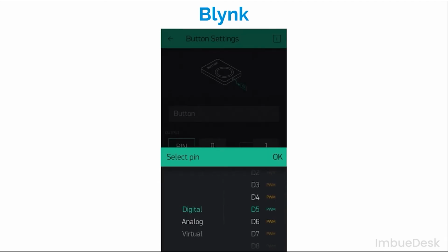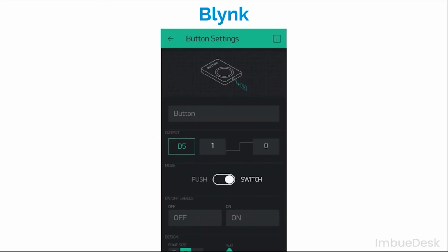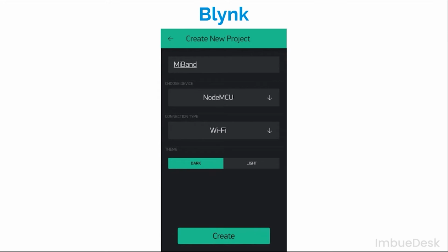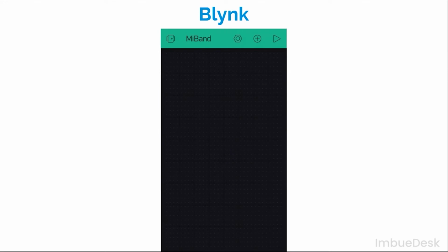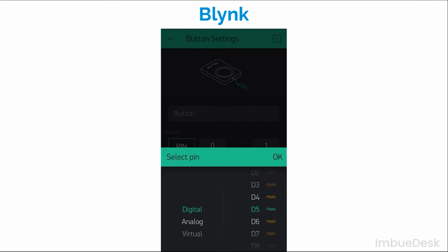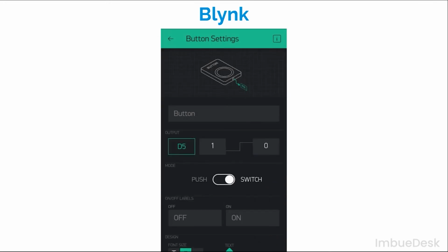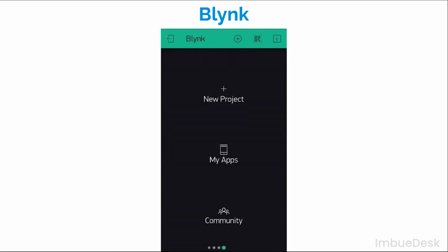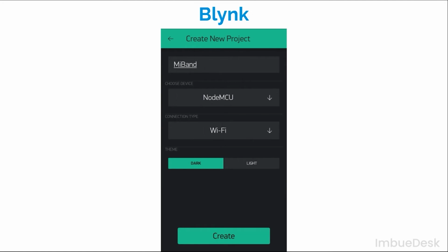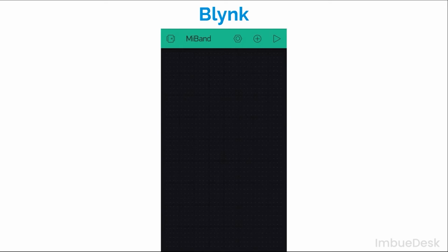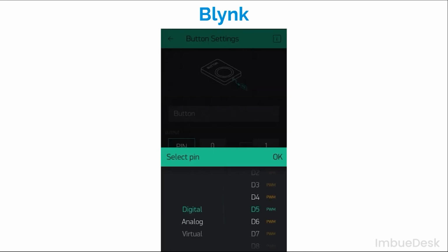So if I get an analog sensor value, it will be reflected here, and when a real LED is turned on, the status will be shown. And hence, when we do not want to disturb the built circuit, or we are short of pins, or we need a separate pin to deal with data, we can use virtual pins. If we code using virtual pins in Arduino and select virtual pins as shown in the GIF, data will be reflected in Blynk accordingly. So simply, that's how Blynk works.